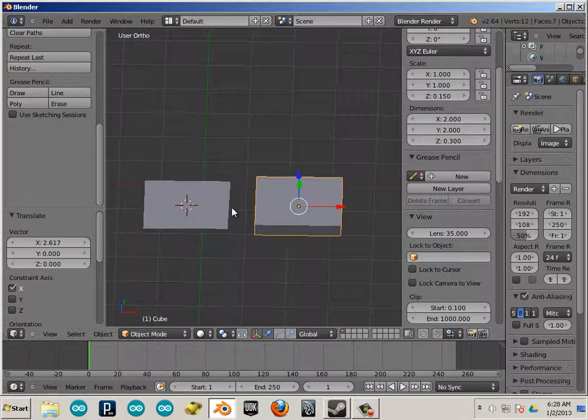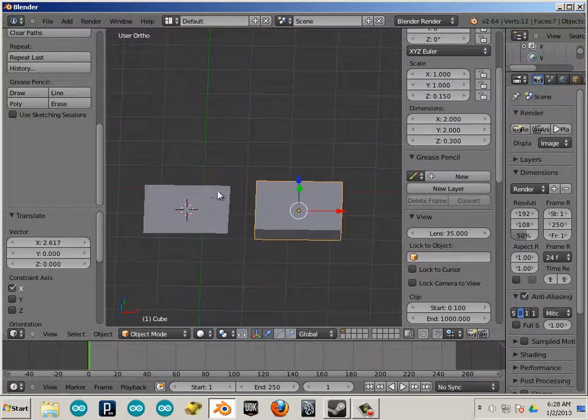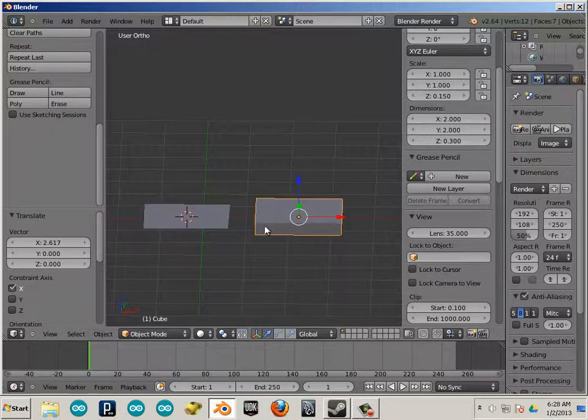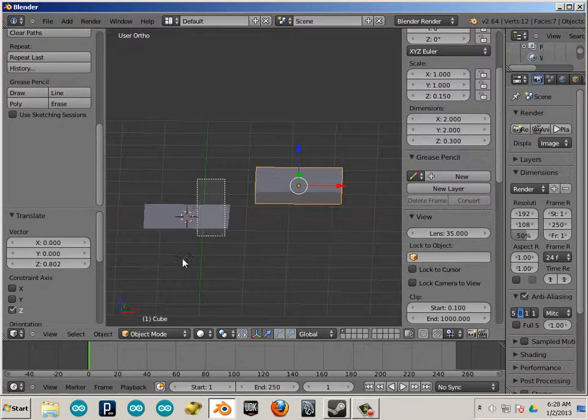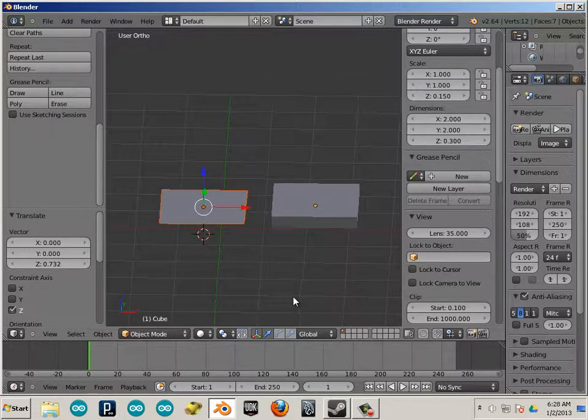Alright, so hopefully that's everything that you should not do. Non-manifold geometry, bad. Surface direction, multiple different directions, bad. Thin does not print if it's not a volume. Volume, not a volume. Alright, that's everything component-wise. Let's look at everything object-wise.